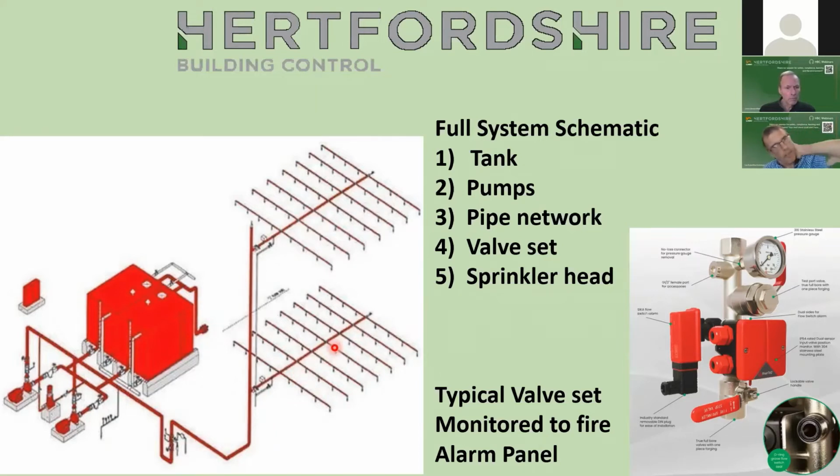Now, from a hydraulic point of view, it works very similar to your radiators at home, if anybody's balanced their own radiators out. Because if you can imagine, the 2 things that are going to make a hydraulic difference to this system are the head, the distance from the water line of the tank to the highest and most distant sprinkler head. So by the time the water pressure gets there, it's going to be substantially lower than it would be for, say, this sprinkler head, which is the closest to the system. And it's a bit like your furthest radiator in the house.